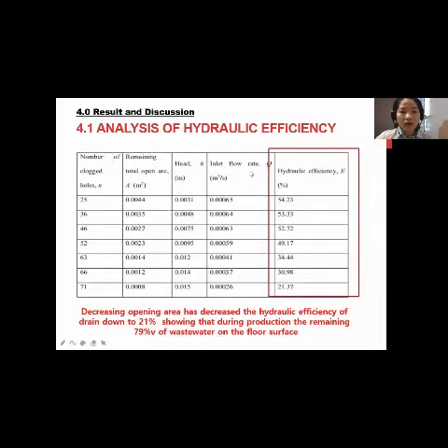And then I calculated the inlet flow rate or the hydraulic capacity of the current drain, and also its hydraulic efficiency using the two equations just now in chapter 2 at different numbers of holes clogged, where the total number of holes of the current drain is 81. For example, when 71 holes are clogged, the inlet flow rate becomes very low, and also the hydraulic efficiency.